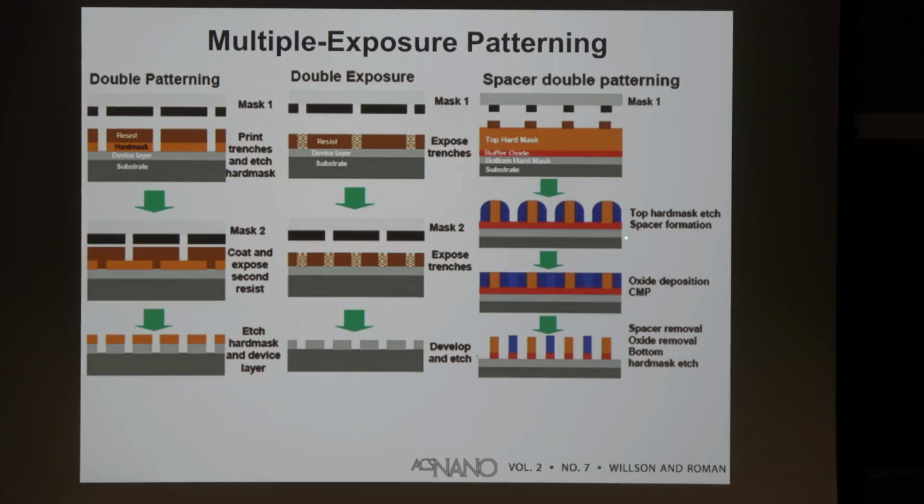So you grow some kind of spacer layer by chemical vapor deposition or by atomic layer deposition or some kind of process that uses the fact that you could grow stuff on the sidewalls. Okay, so you've grown stuff on the sidewalls of these features that you made. Then you can take these negative areas and you can deposit what you want in there.